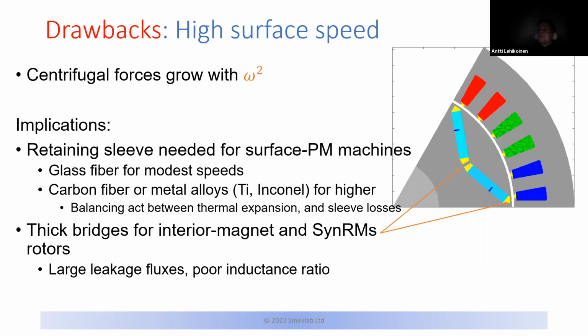So there won't be any AC losses induced in the carbon fiber composite. But on the flip side, it's also an insulator thermally speaking, meaning cooling the rotor just got more difficult. And when you have magnets in the rotor, you very much have to cool them, because otherwise you will simply kill your machine if you overheat your rotor.